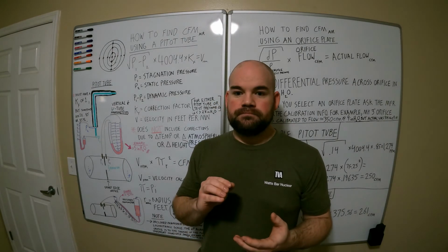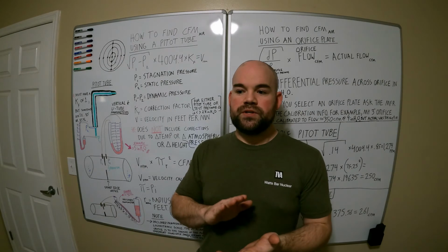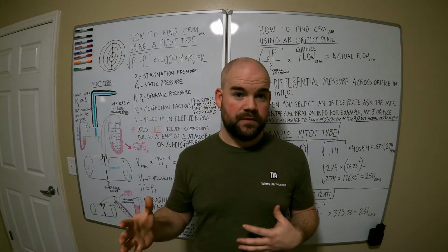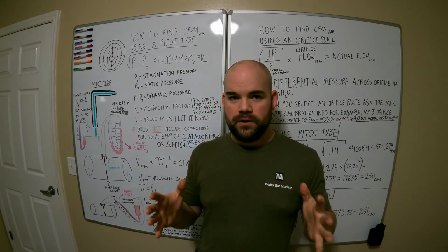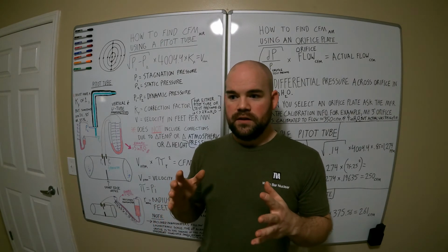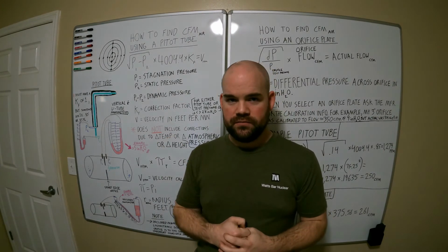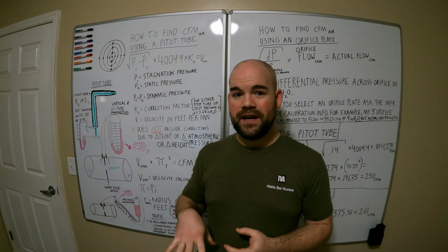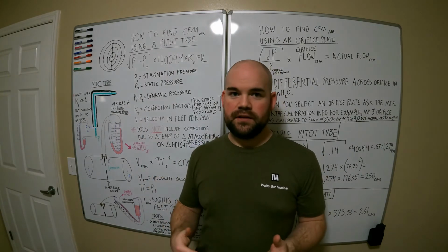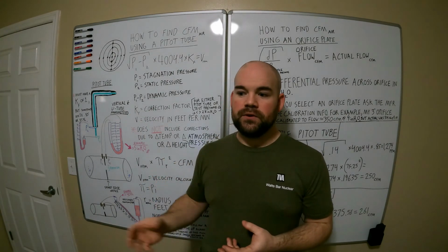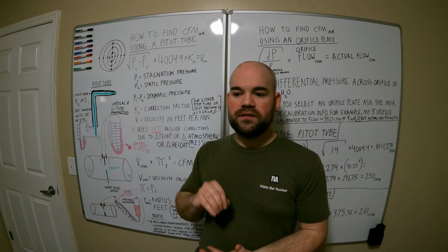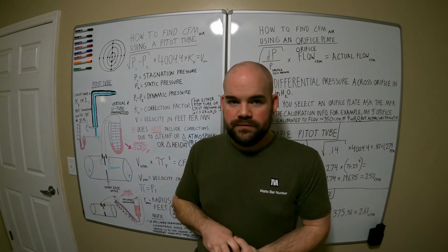But what's important to understand is 1 cubic foot of air. We're measuring CFM, how many cubic feet of air per minute. 1 cubic foot of air does not change with speed. If you put positive pressure, pounds per square inch, above the 14.7 ambient atmosphere, boost, right? If you're increasing the amount of pressure inside the intake manifold plenum, that does not make more CFM.